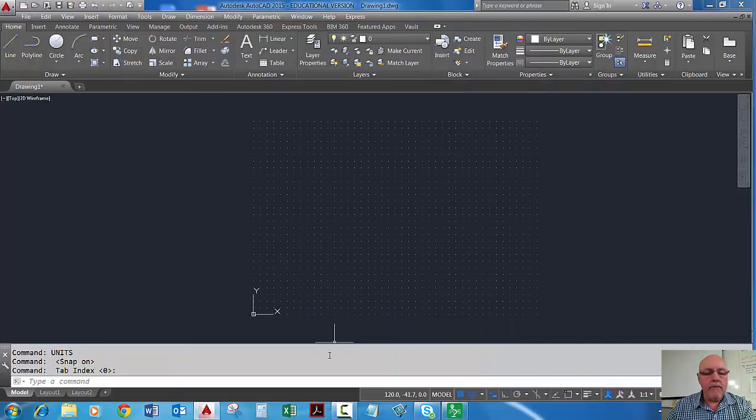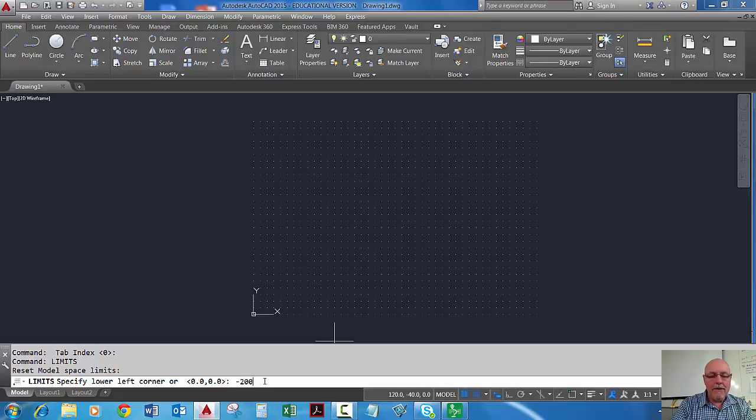So to go to limits, I recommend just typing in the command limits. Then -200 on the X and -150 on the Y. Oh, my number pad's not working. So -200, comma, -150.